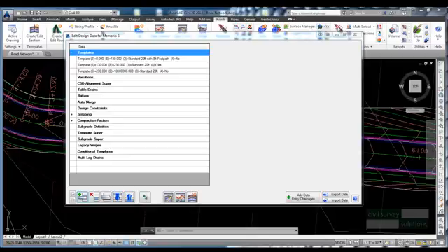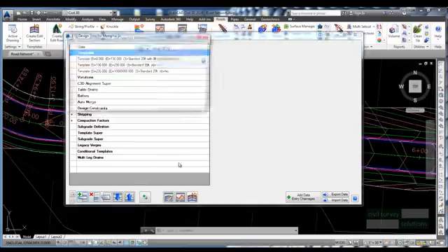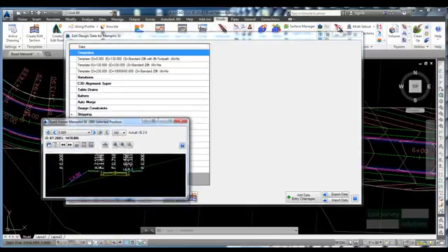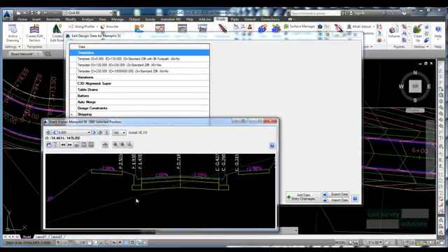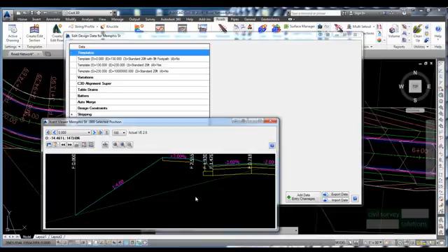The daylight slope projection that extends from the edge of the road design to the sampled surface tends to change regularly along the design for a number of reasons. The more common are to avoid covering surfaces and to prevent excessive fill around trees. There are a number of ways to alter the batter projections.